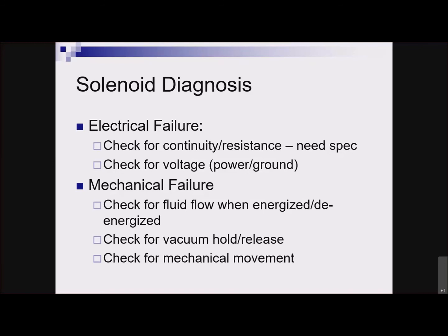And then to check the solenoid itself for continuity and resistance, you're wondering, is the coil broken inside it? The only problem with checking resistance on it is you either need a specification or you need a known good one for comparison. Well, what I've done a lot of times, take a little 9-volt battery, that's usually enough, and a couple jumper wires, and as soon as you touch that 9-volt battery to the solenoid terminals, you're probably going to hear it click. Then you're going to know electrically it's okay.